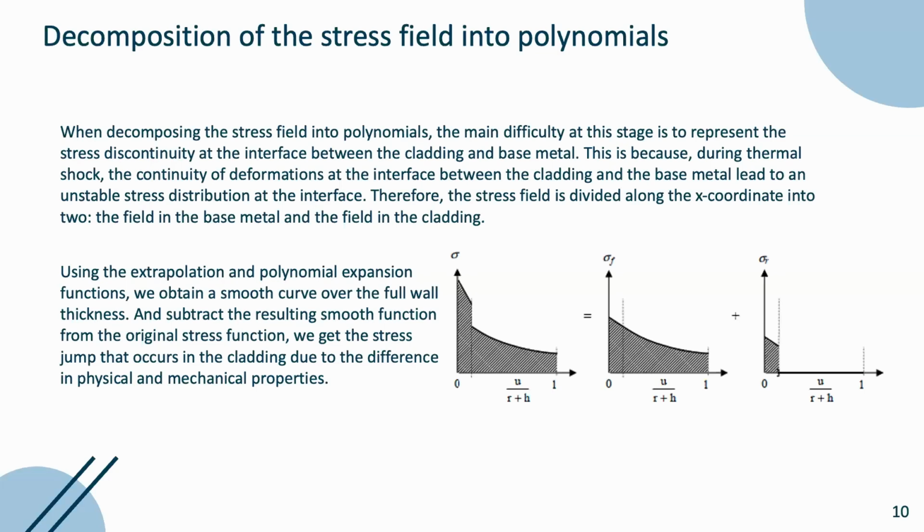Using extrapolation and polynomial expansion functions, we obtain a smooth stress curve for the full thickness, and using the superposition principle, we obtain the stress jump in the cladding.